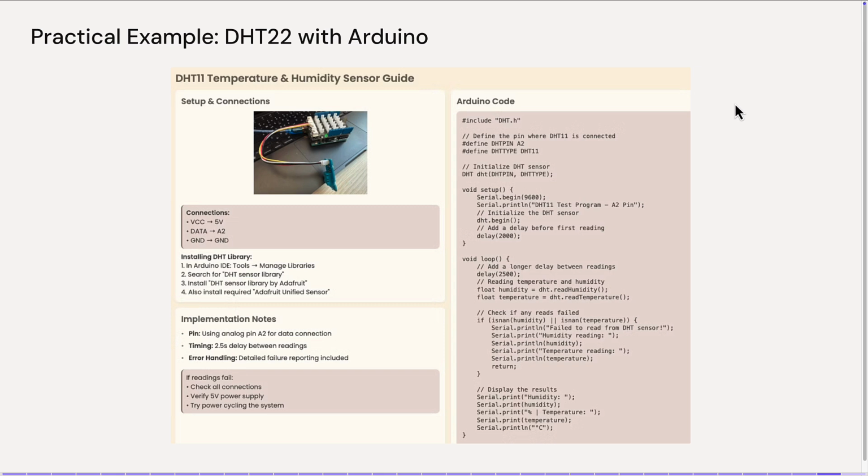So here we connect to a serial port. This is the baud rate, if you remember. Okay, the speed of sending the data. So we will have 9,600 bits per second. And finally, we will show these values using Serial.println and the visualization.